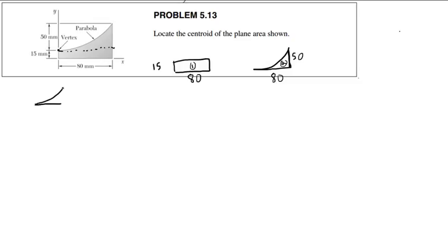The spandrel, on the other hand, gives us the dimensions A and H, and it states that the x bar, measured from the origin here, is located at 3a over 4, and the y bar, the vertical centroid of that piece, is at 3h over 10.